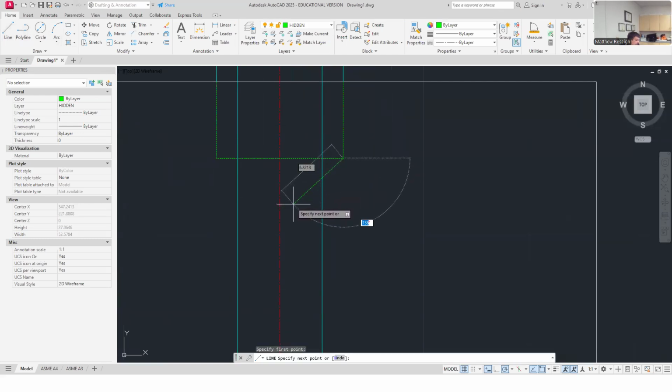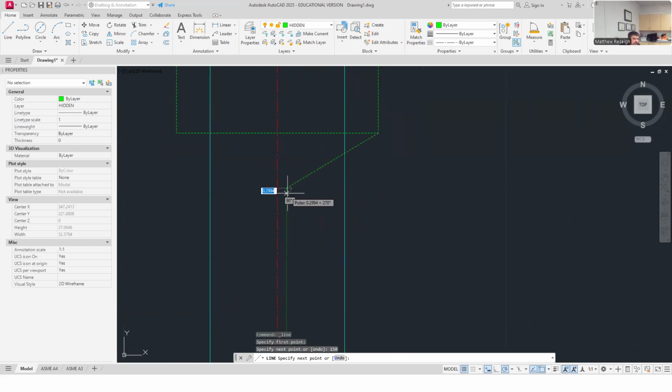I'm going to tab over to 150. And I accidentally hit enter, and so it drops. So I use that extend command a lot. I put in the degree that I wanted, and then I hit enter, and it put in that line length for me. I like that extend. It's better than me pulling grips sometimes if I'm trying to be accurate.